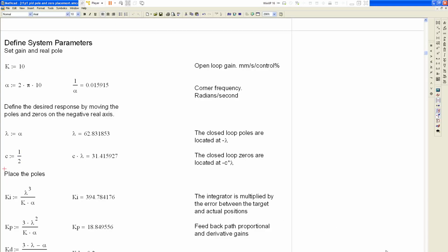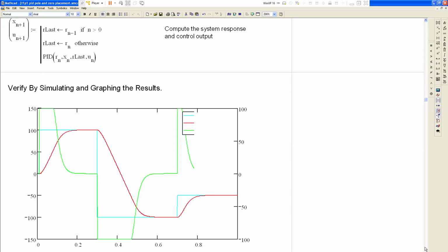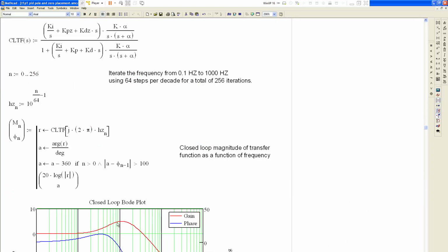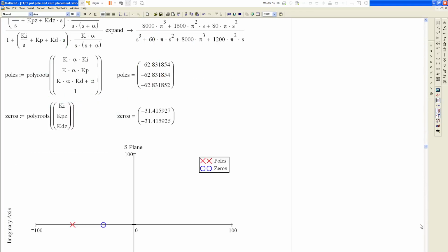So now the zeros. You can see that there's an awful lot of overshoot, and you can see this by the Bode plot. So at 2 hertz, there's a little bit of overshoot, and there should be a little bit of phase lead. And what you can see is that these 2 zeros are 1/2 of whatever the 3 poles are. So as you scan from the origin going to the left, these will start to affect the response first. So they'll start adding gain and phase lead. And then eventually, as you approach the poles, they start adding phase lag and a decrease in gain.